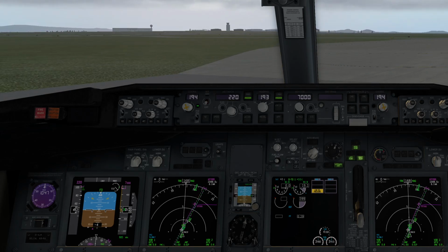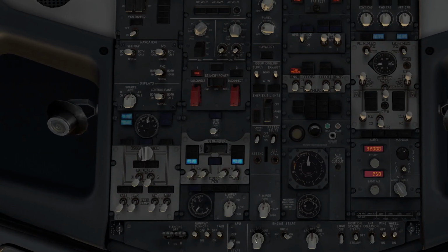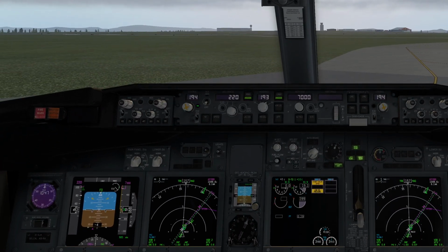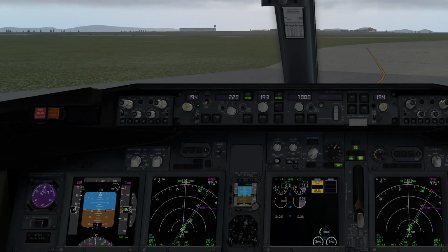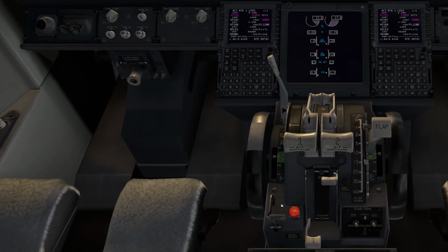Okay, starting now engine number 1. Same procedure. EGT lights illuminate, fuel flow light illuminate, and N1 rotation and N2 is increasing. Operation complete. Set parking brake. Parking brake is set, and 2%. Disconnecting tow. Stand by. Fuel run.